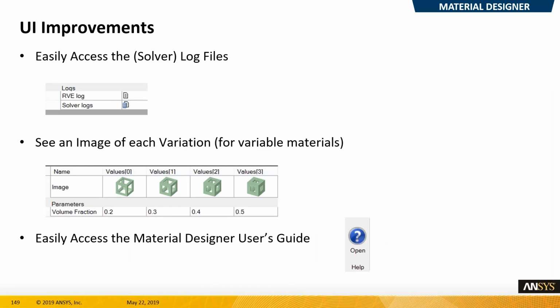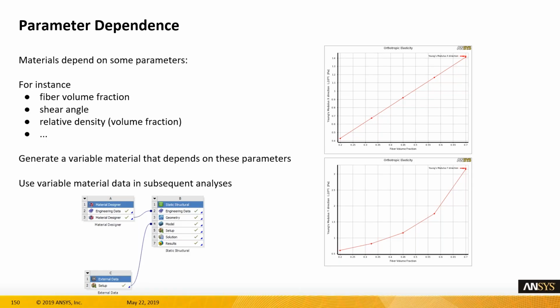You set the fiber volume. That is pretty simple. That is how much fiber versus how much resin is going to be in the module. Parameter dependence, as you can see, is mostly linear for the time. They're working on a non-linear version of it, where you can have input that is non-linear, but it's not ready yet. For the time being, it's only capable with the linear material inputs, but it will subsequently result in a non-linear autonomic output, depending on which kind of parameter you apply it to.